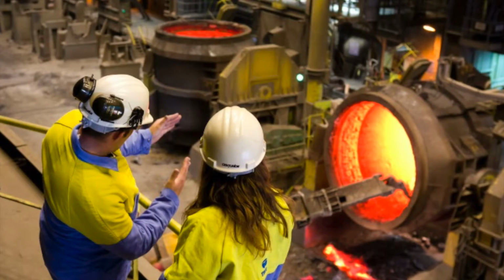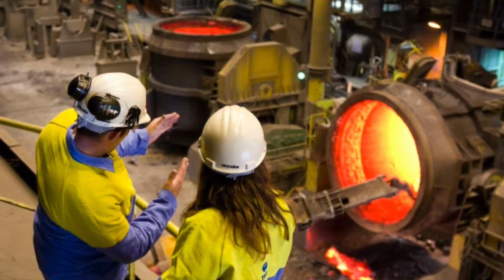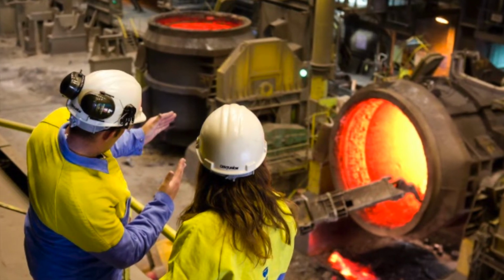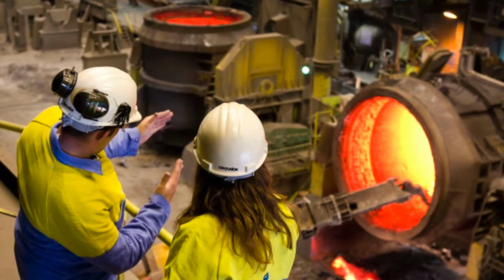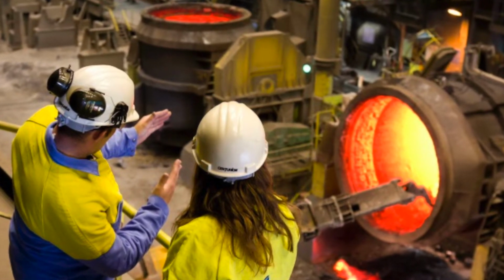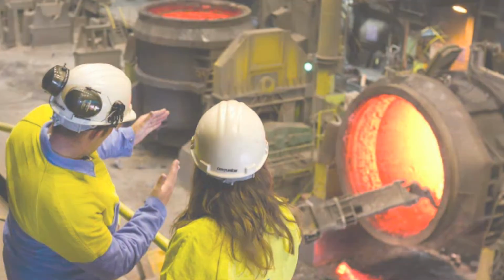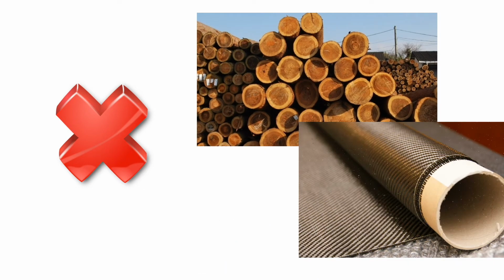The next extrapolation involves the hardness of the steel chosen. Since heat-treated 4340 is very hard, drilling into softer materials should put less wear on the drill bit, making the selected material acceptable for softer materials. Essentially, the extremes of hardness and drilling forces were assumed, so that the material selection can be extrapolated for all material and hole sizes. Note that this material selection will not consider the types of bits required for wood or composite materials.